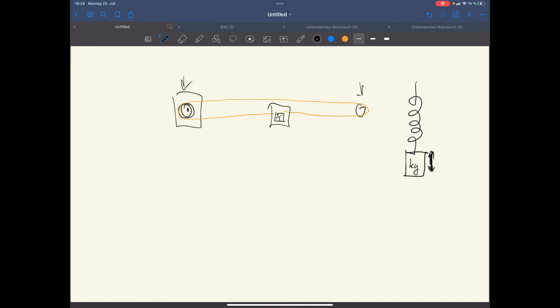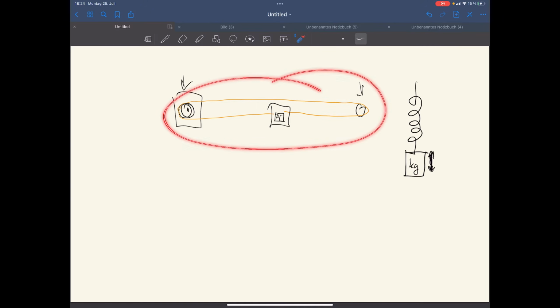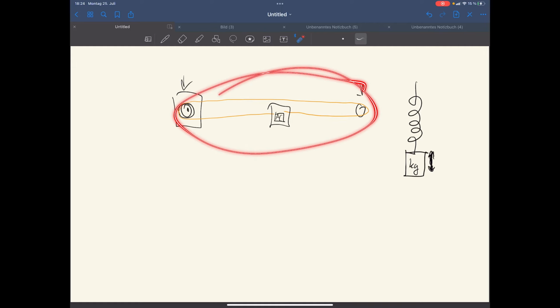And that is what we basically assume within the printer. We assume a bunch of those. And now what is really interesting, they can be coupled or not coupled, which basically means if we have two or more of those kind of oscillators within the printer, they can either react to a specific frequency on their own, which is a good case because then we just get a peak in the frequency profile, or they can do some nasty things like when they are influencing each other and they get into weird modes, and that's something we don't want to have.